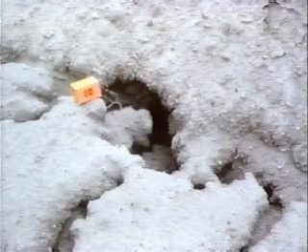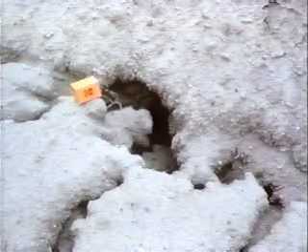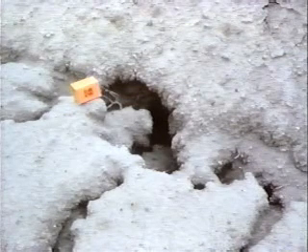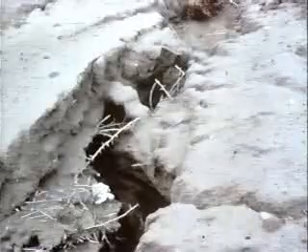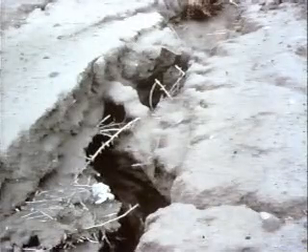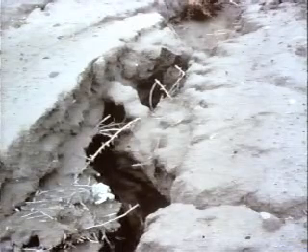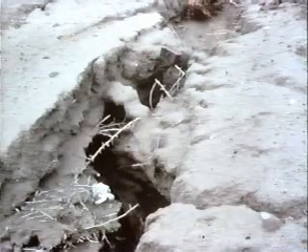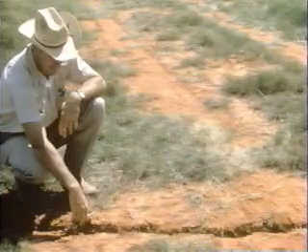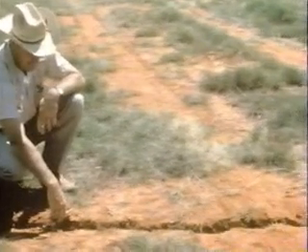Deep desiccation cracks that extend through the core could conceivably cause a breach of the dam if the reservoir rises quickly and the soil doesn't swell rapidly enough to seal the crack. Also, if heavy rains fill deep cracks, portions of the embankment material near the cracks may lose strength and a slide may result. Next, let's look at transverse cracks.